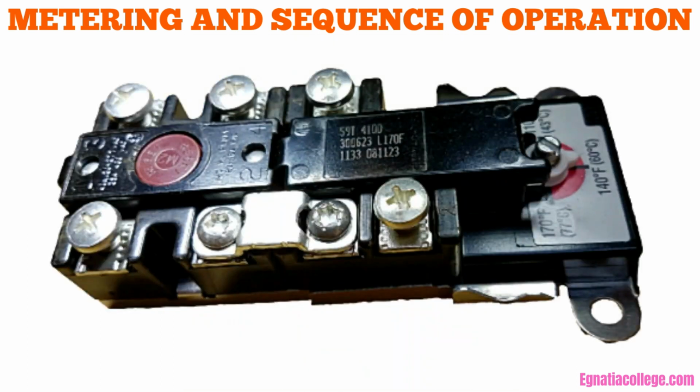2. Connect the water heater in a flat rate arrangement. The utility supplies power to the consumer via a 4-wire cable. This contains the 3 feeder lines and a 4th wire to control the water heater during peak demand periods.